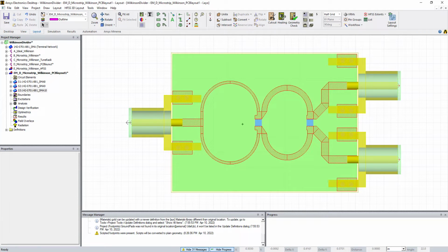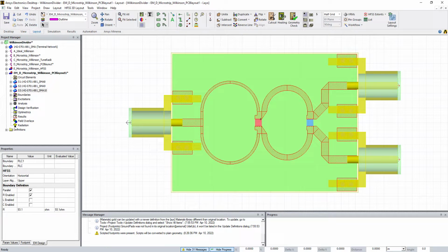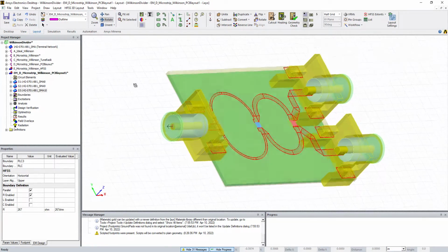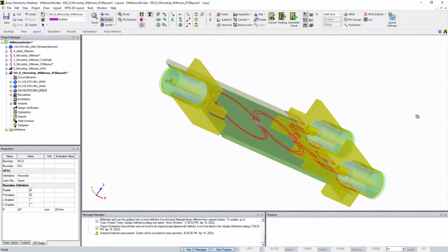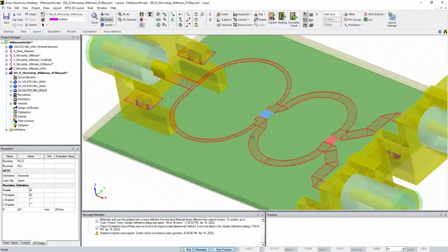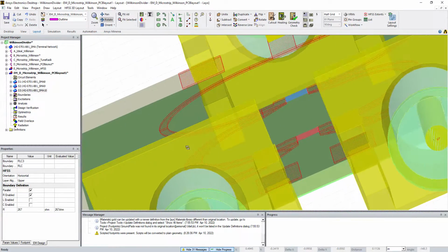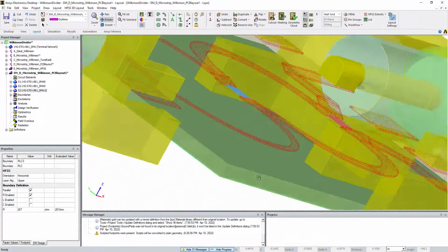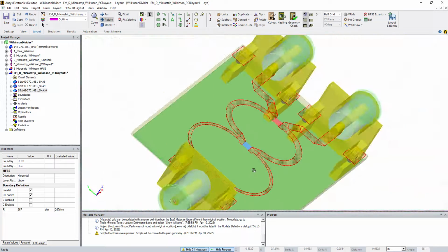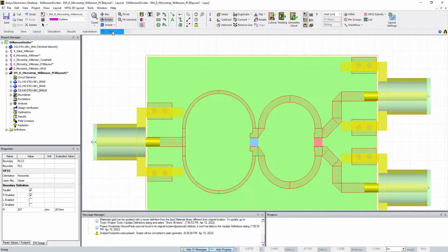So what did we just do? We just put in, from there to here, two ports that you're going to put a lumped resistor of 93.1 ohms across, and there, from that edge to that edge, 267. So when you rotate it, you can see that what you're actually doing is putting a thin film lumped resistor right there between those two edges. See that? That's pretty cool. Although we're going to do it with an SMT resistor, but still, that's how you do that.